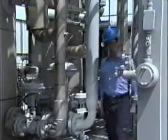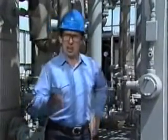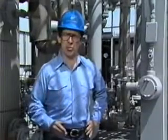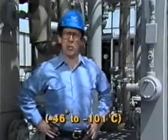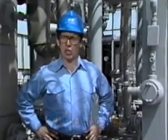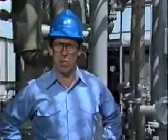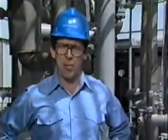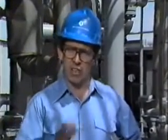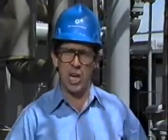Cryogenics is the newest and most energy efficient of the three processes. In the cryogenics process, the natural gas stream is cooled to extremely low temperatures, in the range of minus 50 to minus 150 degrees Fahrenheit. Instead of using a refrigerant, cryogenics uses a mechanical method to cool the gas which liquefies the ethane and heavier hydrocarbons. The liquids are then separated from the methane. Cryogenics does require additional compression to raise the pressure of the methane. However, when compared to lean oil absorption and refrigeration, cryogenics has moderate energy requirements.